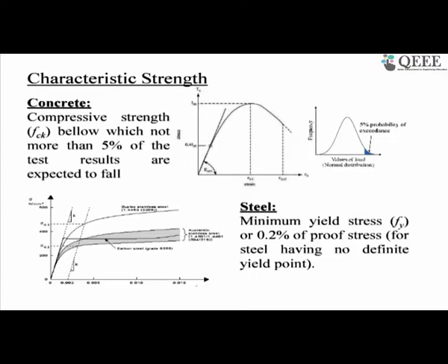So stress is linearly proportional to strain, and the slope of this linear segment is called Young's modulus. Then, when the stress reaches a certain value, even with increase in strain, the stress remains almost the same. So we have a plateau region. It says that initially when the material made of this steel is loaded, the relation between strain and stress is linear. So with increase in strain, stress is also increased linearly.